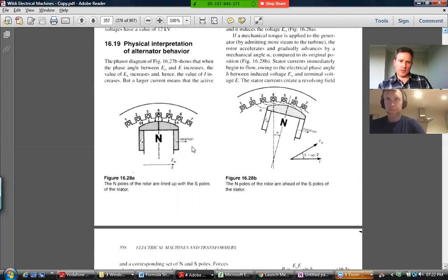Okay, so under normal situations, if there's no torque and everything's just spinning freely, the rotor is spinning, but there's a rotating magnetic field produced in the stator because the machine is on the three-phase line. Like we had for an induction machine, you've got the peaks and dips of the three phases causing a rotating magnetic field. And as that field rotates, if this magnet lines up with this pole at all times, then there's no torque and the turbine just spins freely.